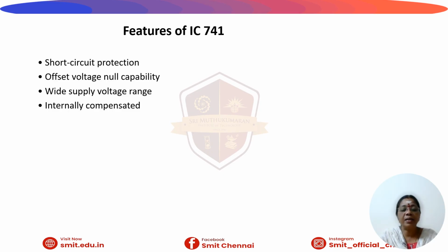Then internal frequency compensation is achieved by a built-in 30 picofarad capacitor, which helps to stabilize the circuit and prevent unwanted oscillations without needing external components. Then short circuit protection is achieved using the output stage, which includes an internal circuit that provides overload and short circuit protection, which safeguards the device from damage.